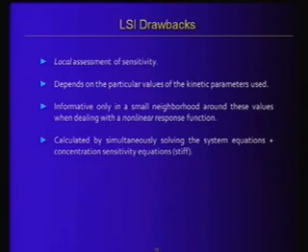So these are some drawbacks which you cannot evaluate very easily if you don't know much about your system. But one problem that you have is this: if you want to calculate these derivatives rigorously without approximating them by means of finite differences or whatever, you can do that. Because you can go to the original differential equations, differentiate them on both sides with respect to k, and you are going to come up with another set of differential equations in terms of the derivatives, the sensitivity indices. So you can come up with differential equations that describe the evolution of the sensitivities.